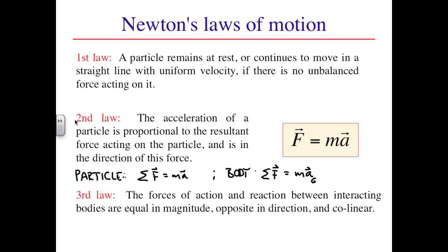Because a body's motion is generally a superposition of translation and rotation, every material point in the body generally experiences a different acceleration. This body equation tells us that we can ignore all those different accelerations and just focus on the acceleration of a single material point, that coinciding with the center of gravity. In this way, body motion appears similar to particle motion.